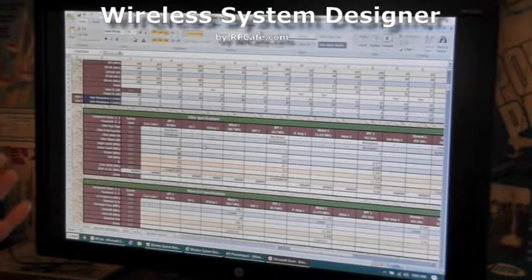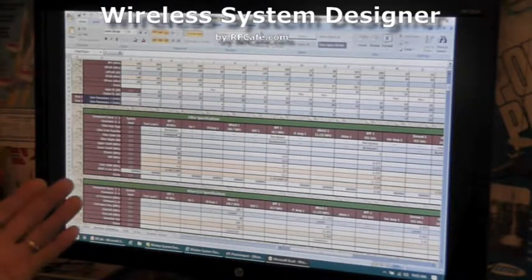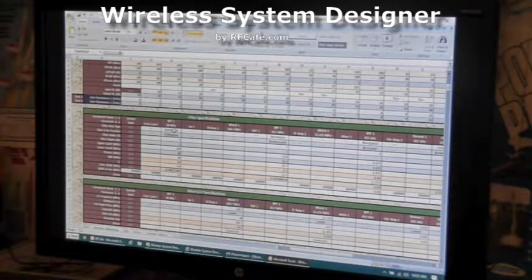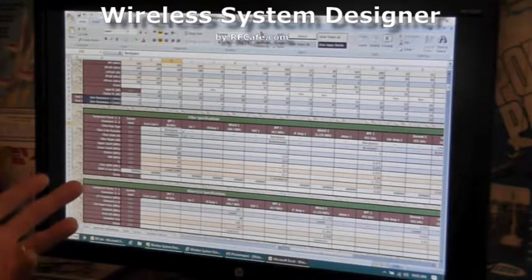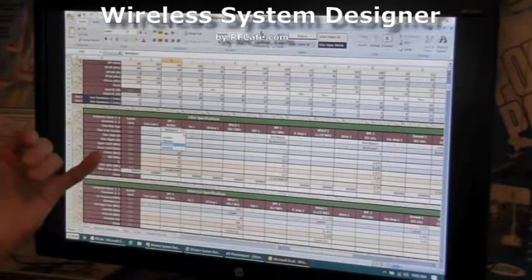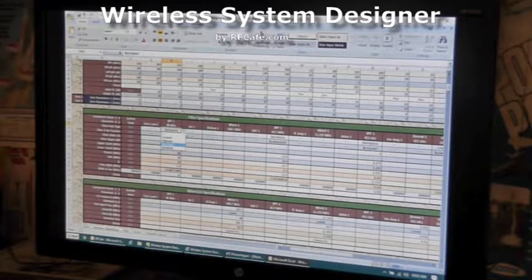You might have another component, an amplifier or a circulator or something like that, that has a frequency response that's nonlinear that you want to model in the system. So you can pick one of these standard options. I have, again, used the drop-down menus provided: low pass, high pass, band stop. You can use any of them. They use the standard textbook formulas, nothing special in there.